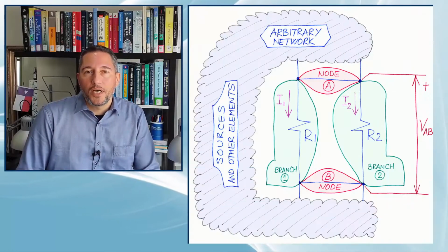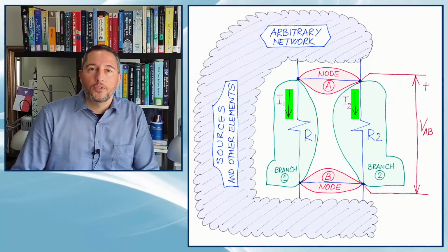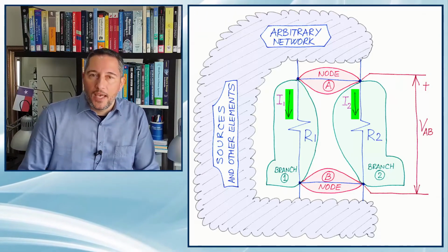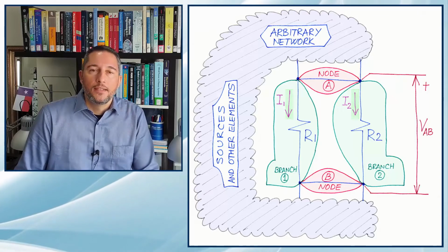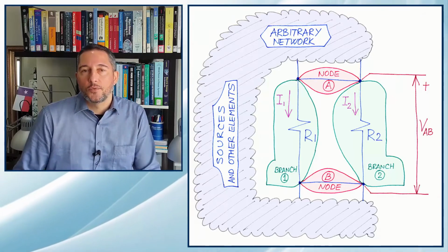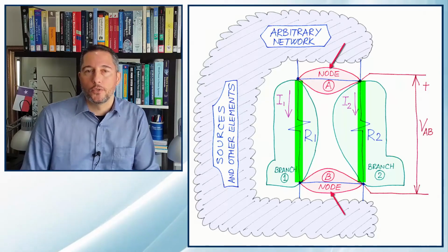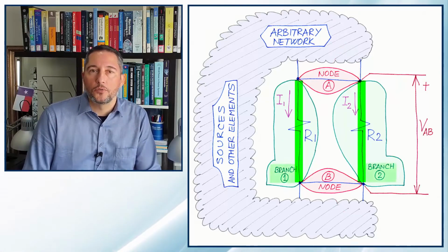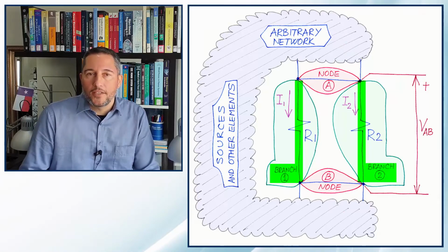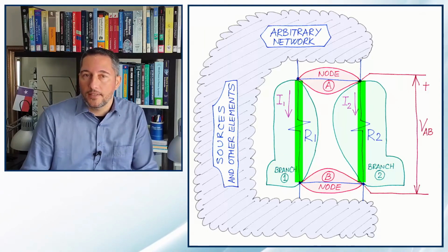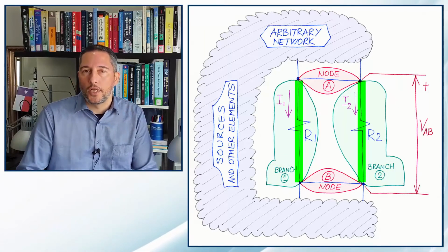You see, when we talk about parallel currents, we talk about currents that flow through two different paths, and those paths happen to be parallel. Now, in electrical circuits, when we have a couple of nodes and we have certain paths between those two nodes, those paths are actually called branches. So within one branch, we have one current that flows through that branch. So if we have two parallel paths, that means we have two parallel branches, and each branch will have its own current.